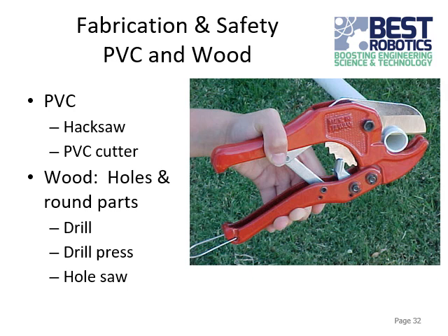Sometimes they can make the edges a little rough, and the hacksaw can do that too sometimes. So once you cut PVC, if it's an edge that's going to be exposed, then it's a good idea to clean it up with a piece of sandpaper or something to smooth it off. But if it's going to go into a PVC connector, then it doesn't matter. Nobody's going to see it. Nobody's going to care. So you don't need to in that case.